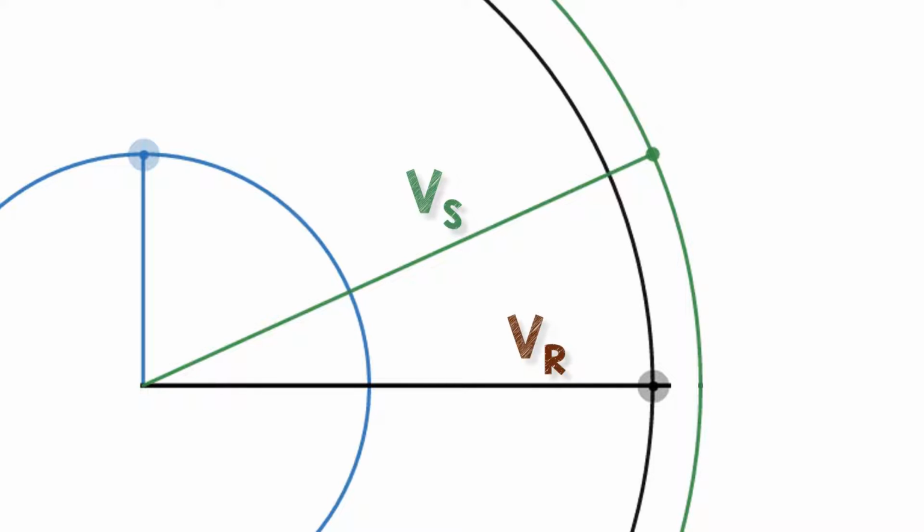The resistor voltage VR is the adjacent side of the right-angled triangle and starts on the x-axis. The length of the VR vector does change as the supply frequency changes, depending on how much voltage is across the resistor. The inductor voltage VL is the opposite side of the right-angled triangle and starts on the y-axis. The length of the VL vector does change as the supply frequency changes, depending on how much voltage is across the inductor.